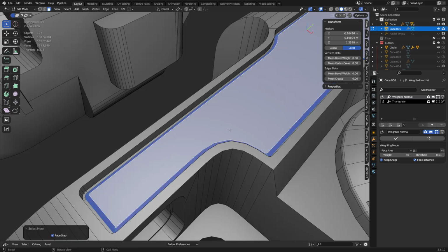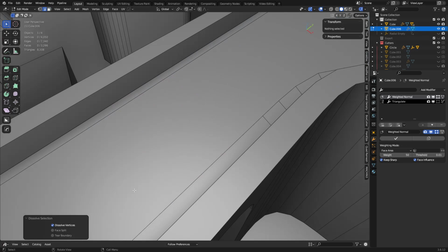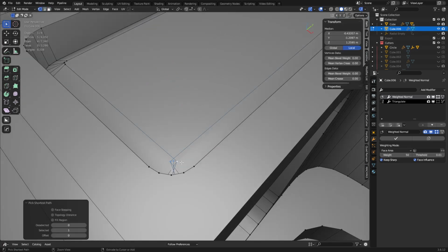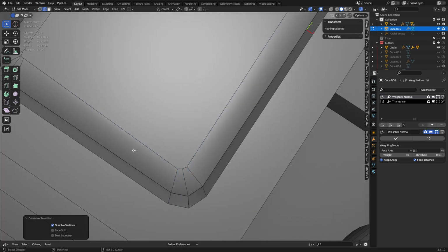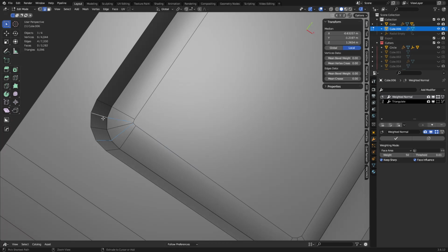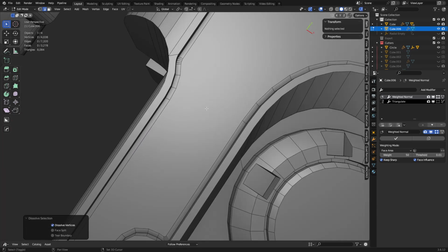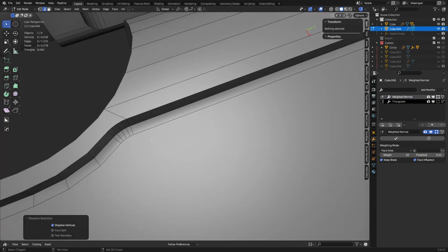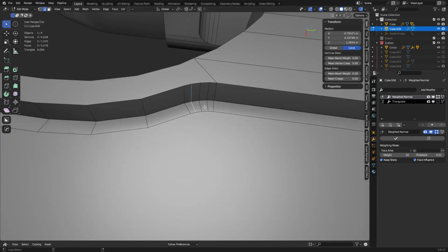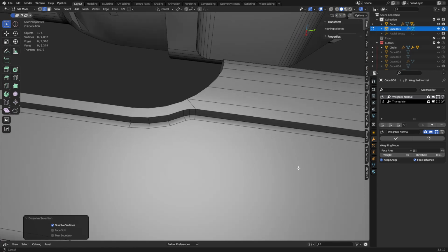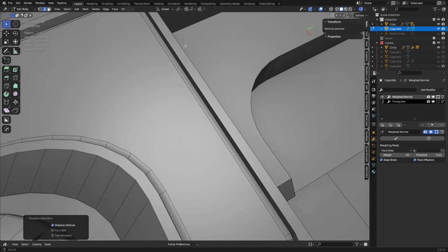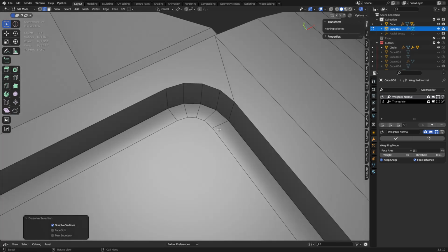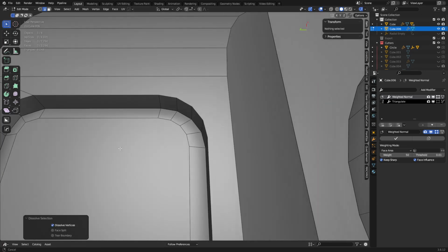So some things you can select more, select boundary loops, Control X, dissolve that in there. You can see we have a little issue here. Pull those out. I don't think I need those extra edges in there. Doesn't seem to help much. So you would want to set kind of a certain amount of edges for your bevels. Maybe smaller ones end up being 2 segments or 3 segments like that. And you can go through and just dissolve a couple things here or there.